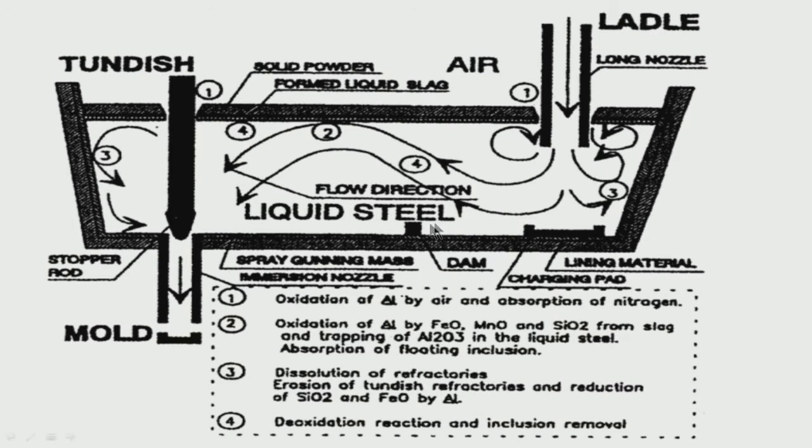Yesterday, in the last session, I had just started talking about what a tundish is, what happens in the tundish, what the issues are, and how we have to be careful during casting, so that there is no exogenous entrapment from the tundish. So, this is liquid steel coming from the ladle. I was talking of the refractory nozzle, this is the refractory shroud, and we must use some argon also here, so that there is no air ingress here. Now, this is the total tundish. From the ladle, liquid steel is coming here.